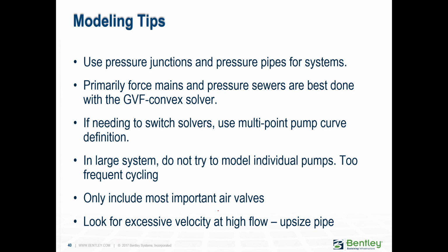And every time you model pressure systems, one thing you always want to keep an eye on is the velocity when you have high flows, because pipes that have high velocity are what we call bottlenecks. So maybe you're wasting your pumping energy in those bottlenecks in the system. So look for those and upsize if possible.